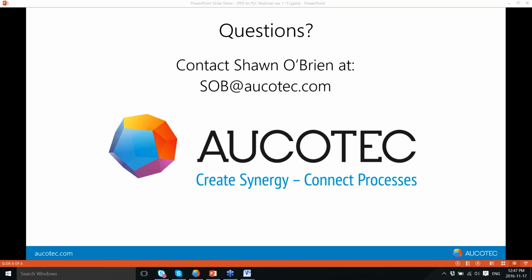And we do have our first question here. Ryan, while doing the loops, how do you assign wire numbers? Let me take that on. It's Malcolm Owen here. We have several different ways to assign wire numbers. Some automatic routines to do that. The wire number can come from what we call an add-in, which can be configured to give you wire numbers in a particular format that you want.